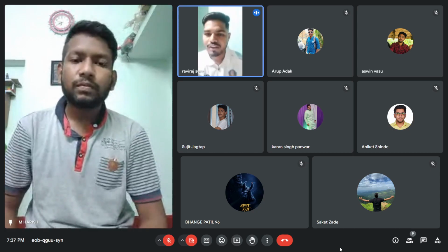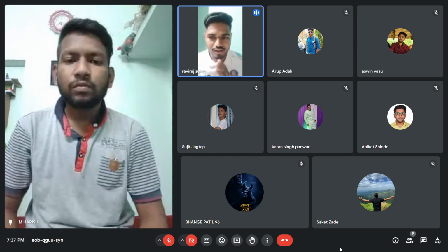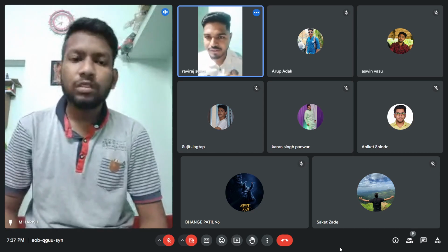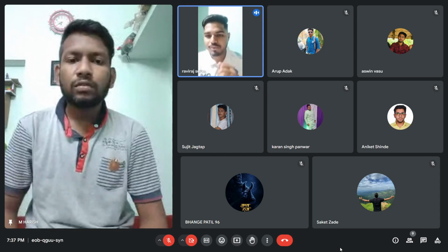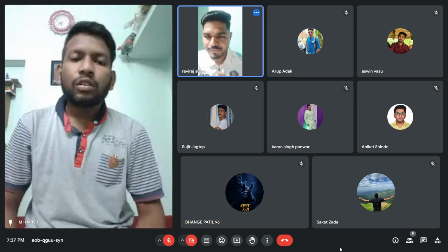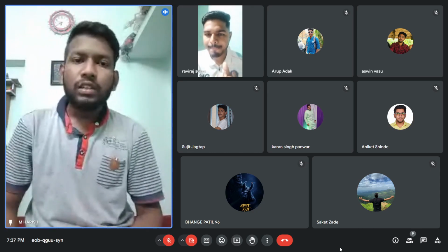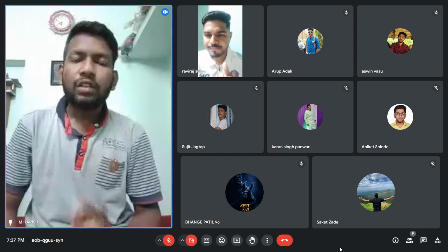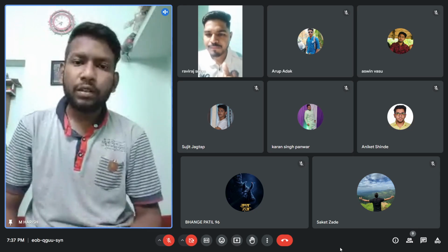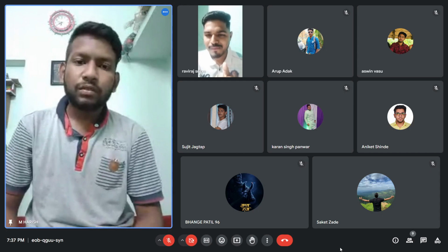Okay, so Harish, you have prepared the compressor topic, right? Yes. So tell me the safeties of compressor. Lube oil low pressure trip, relief valve, then jacket water high temperature trip, fusible bulb, and bursting disc.